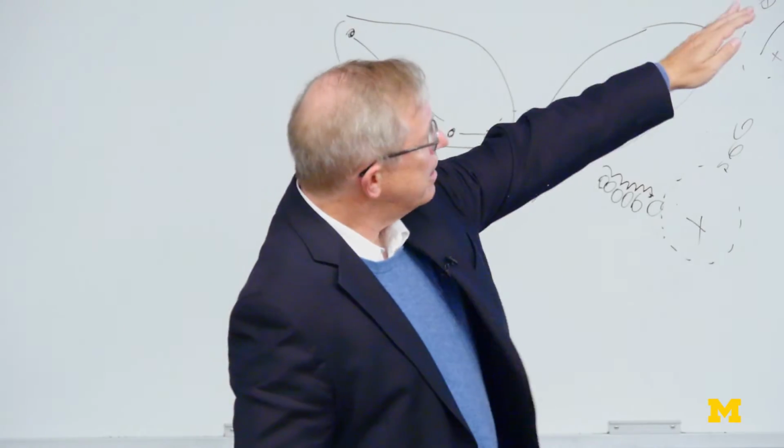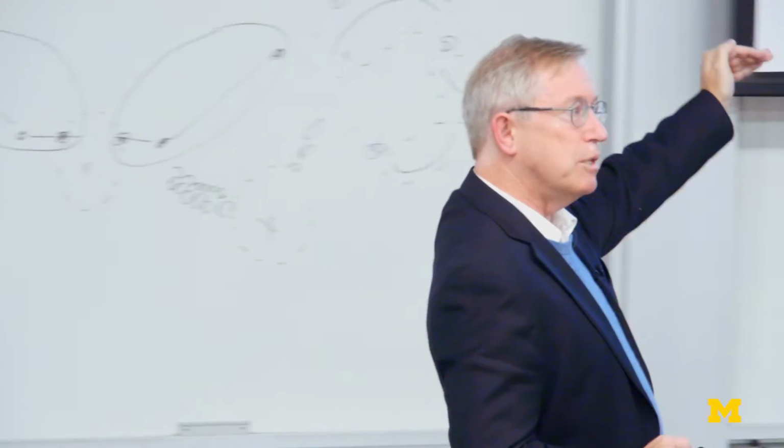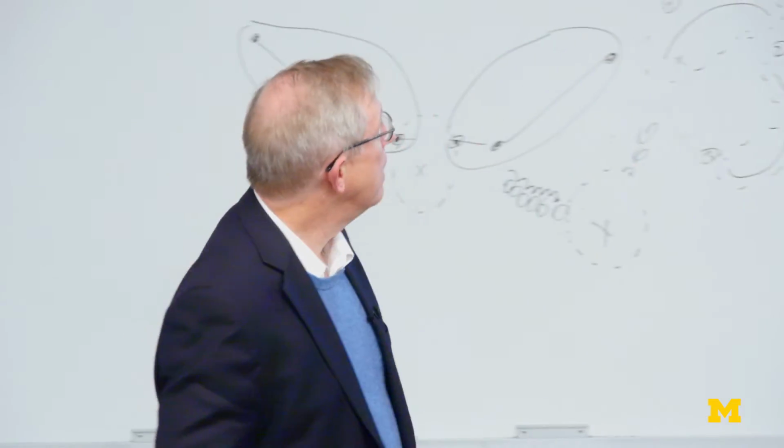So if you were to try to look at a capacity estimate based on this receiver, a digital backpropagation receiver, you get a good sense of what you might be able to achieve, at least a bound on what you could achieve in practice. You might get some kind of achievable rate, at least, out of this sort of thing.